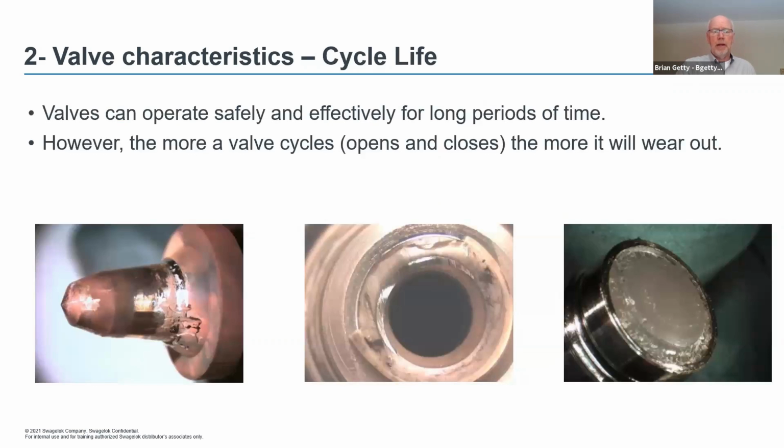And what I've included here, your cycle life. Again, as I've mentioned before, a valve may be installed in a system where it's going to operate once a day, once a year, once every 6 years, God only knows. Or it could be a valve that's going to be turned on and off once every 2 or 3 seconds. Very important to know, so you need to know what your cycle life requirements will be. And don't forget, any valve that you cycle even once, you're creating wear in that valve. All valves wear. It's a wearable component.